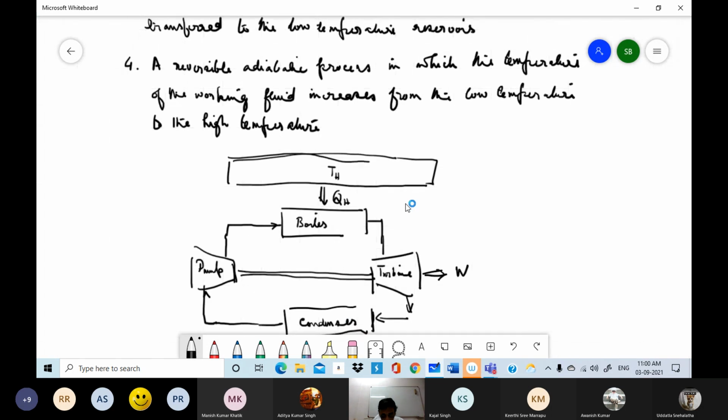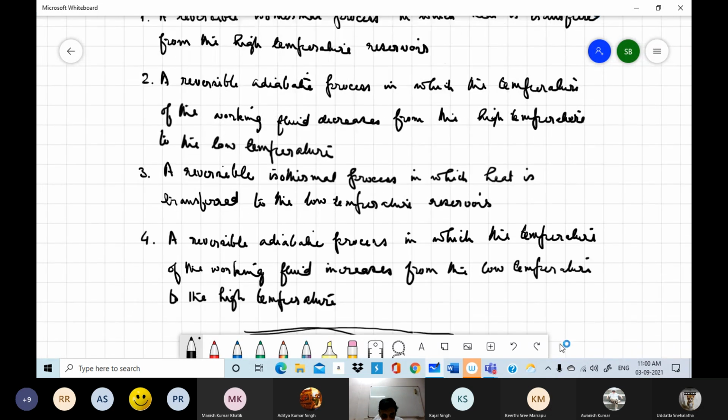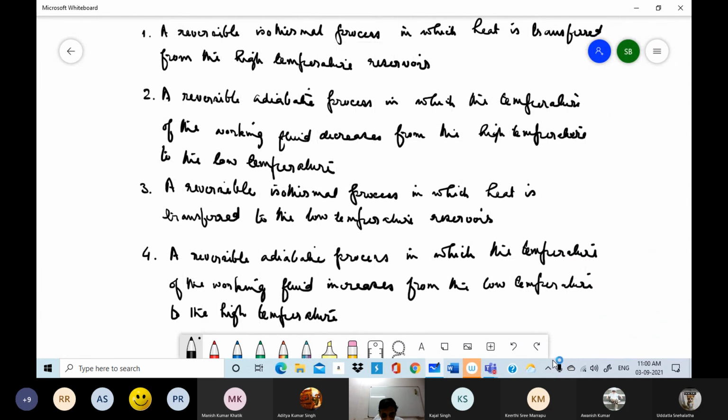After that, we defined something called a Carnot cycle. So the Carnot cycle physically would look something like this. And by definition, there are two isothermal processes. There's isothermal heat addition and isothermal heat rejection. Now, how can you have isothermal heat addition or heat rejection? Well, the simplest case is when a substance is undergoing phase change. The two isothermal processes are connected by two reversible adiabatic processes.